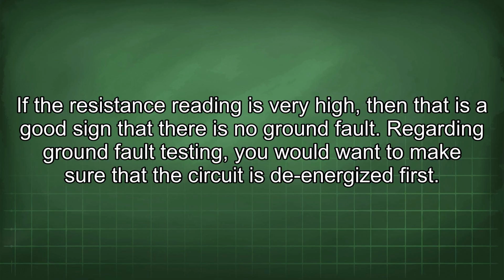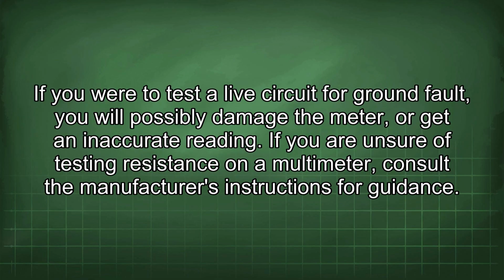Regarding ground fault testing, you would want to make sure that the circuit is de-energized first. If you were to test a live circuit for ground fault, you will possibly damage the meter or get an inaccurate reading. If you are unsure of testing resistance on a multimeter, consult the manufacturer's instructions for guidance.